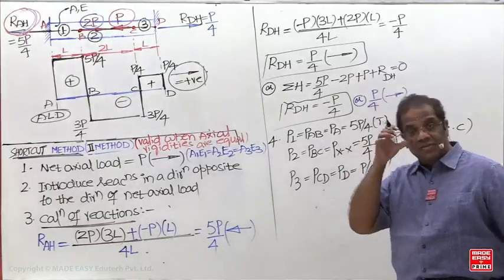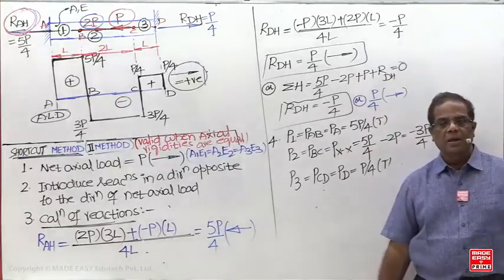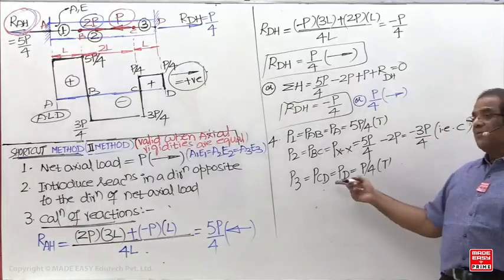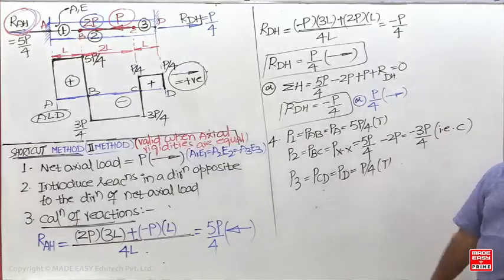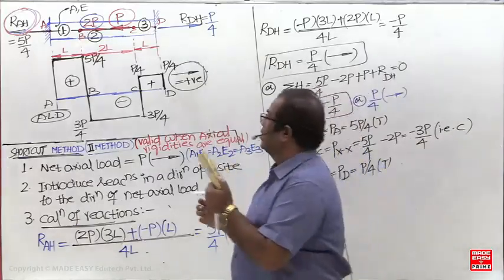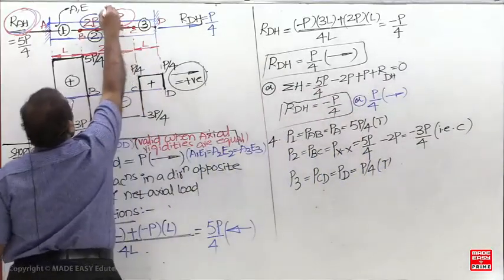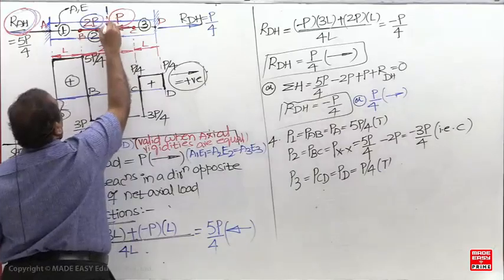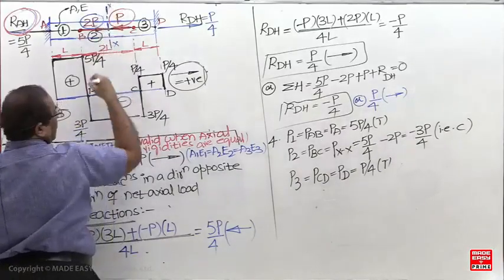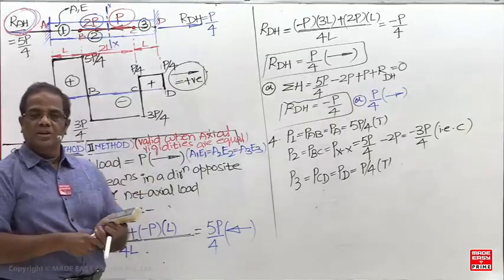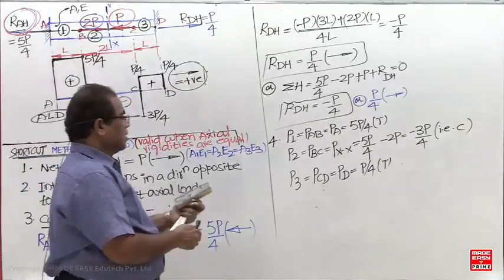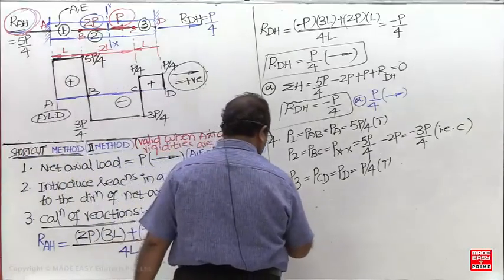So if only one section is sufficient, then it is better to take this. But if you are not thorough, then you can go for the ALD or the shortcut method. Only one section is going to be there, so this is better. When compared to this, this will take less time. Sir, I want to go for the section. ALD, you can draw it, you have drawn it in the previous case. So the remaining is the same: what is the maximum tensile load?